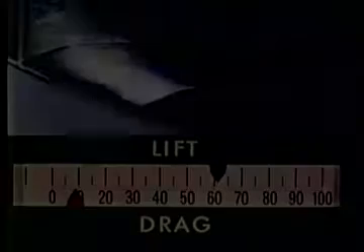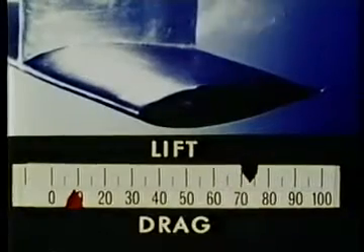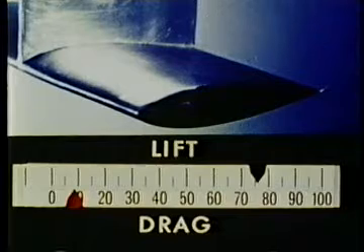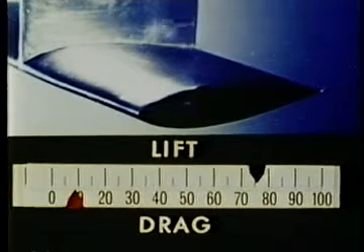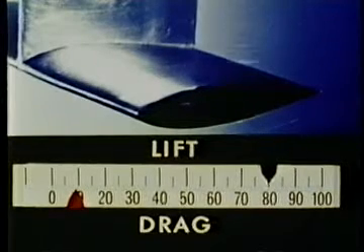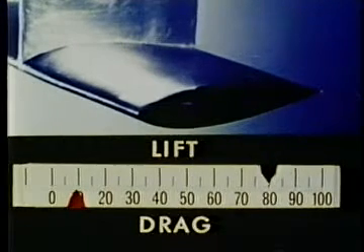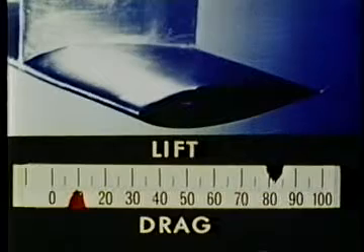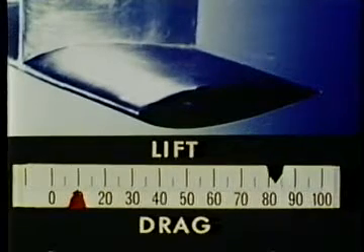The flow speed is constant, and the gauges register the corresponding lift and drag. The ambient pressure is set at a level well above that at which cavitation can occur. We are going to induce cavitation by decreasing the ambient pressure in the test section, keeping the speed constant.